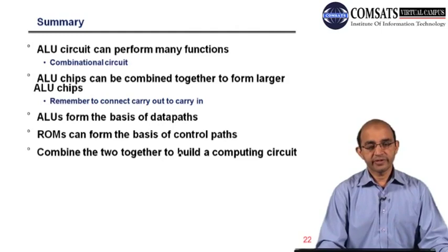For example, if we have a single ALU that can perform operations on 4-bit numbers, and we want to extend the length of the number from 4 to 8 bits, or 1 byte, we need to connect different ALUs in such a way that we can extend the length of the number.